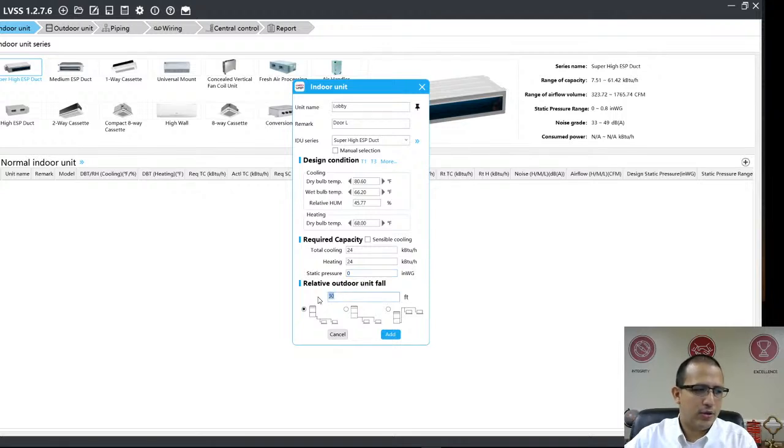I'm also going to enter the length of the piping between the outlet of my outdoor unit and the level of my evaporator. And you can see 3 graphs at the bottom. The first one is if the outdoor unit is above the evaporator, so in a sense on the roof and we're going down. The other one is if they're on the same level, or if the condenser is at the bottom of the building and we're going up.